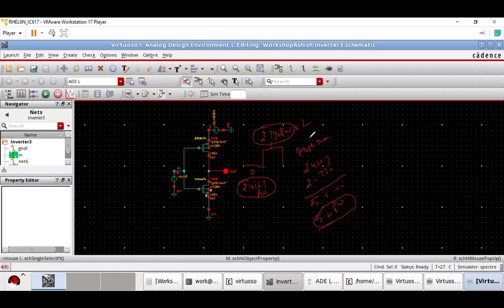You are saying that both NMOS and PMOS are on in that case. I said that I have calculated for 0 and I have calculated for 1. Now I am giving this pulse: only one 0 and only one 1. Total 20 nanoseconds, 10 nanoseconds for 0 and 10 nanoseconds for 1, at the same time.